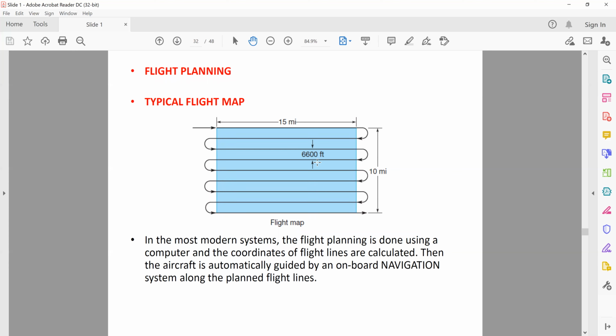And once you have that total area, then by taking a side lap of, let's say, 30%, you can see how much should be the distance at which it should take the turn. So all of these things are planned and then they are set in the navigation, and then automatically the drone flies and takes successive pictures at the instances that you have actually told it to.